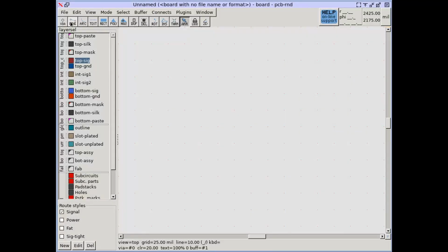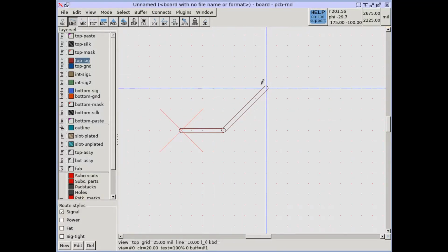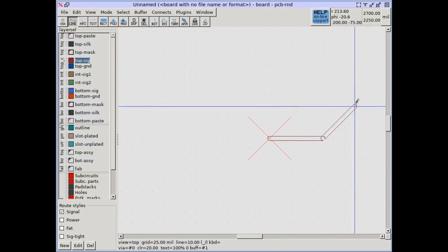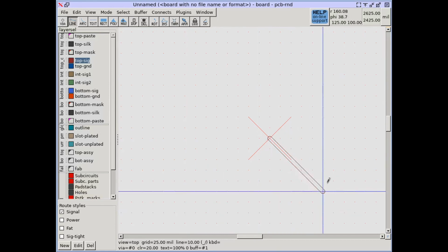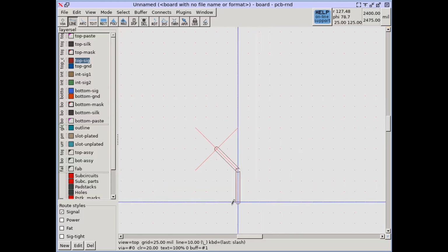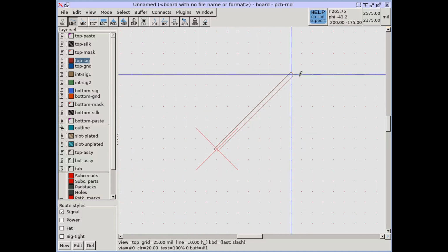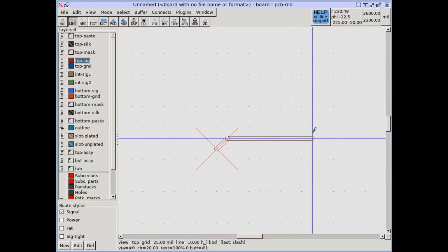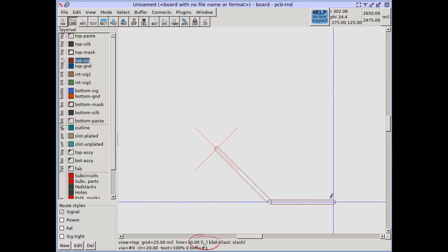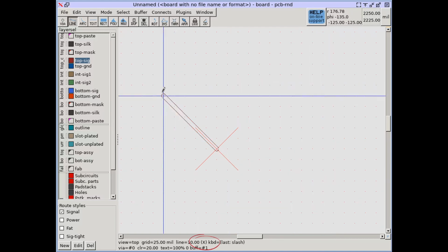Normally, traces are drawn using axis-aligned and 45-degree lines. When line refraction is enabled, two line segments are offered from the starting point that was the first click to the current crosshair position, one axis-aligned, one 45-degree. The slash key, or the key sequence MLF, changes refraction, cycling through different options, refraction ordering and X mode.